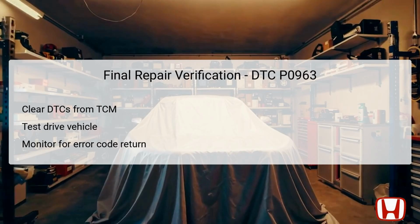correctly. During this test drive, it is essential to monitor the vehicle's performance, paying close attention to any symptoms that may reappear. If all operations remain normal and the MIL does not illuminate, it indicates a successful repair. However, if the error code returns, it indicates that further diagnostics are necessary to identify lingering issues. This verification step is key to ensuring that the repairs have been effective.